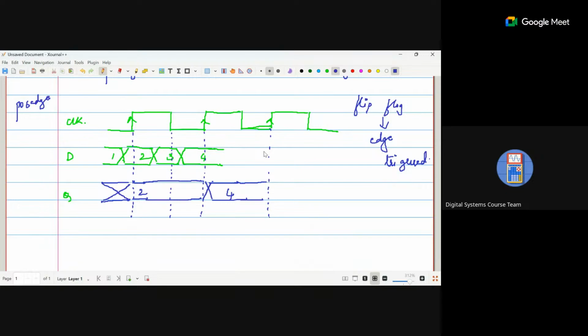And the same thing if you're talking about negative trigger. If we say this is a negative edge trigger, instead of the positive, we'll see the negative side. So if you see the negative side here, till this particular point, it will be considered as don't care, because till then we wouldn't know what is happening as we do not have a negative clock trigger before that.